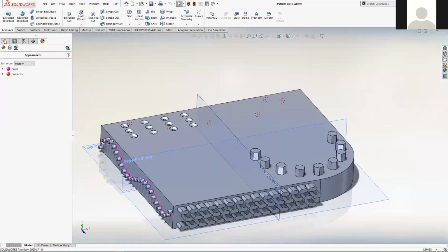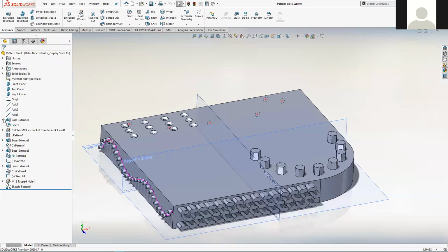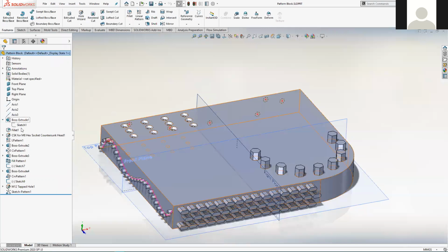So that's the danger. I mean, that's sort of a good word of warning. I'm sure I've talked about this a little bit when we were talking about is it wiser to attach your sketches to the base planes, or is it wiser to attach them to a face of your model? And as I was saying, my overriding advice is if it's possible to attach them to the base planes and not suffer any ill effects because you're doing that, then I would always choose the base planes.